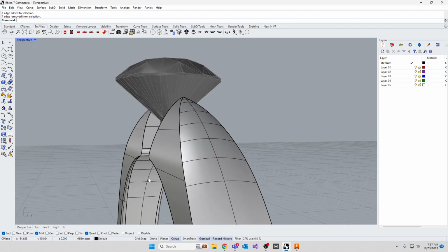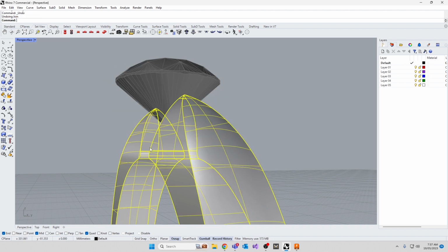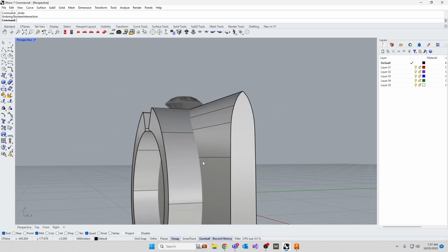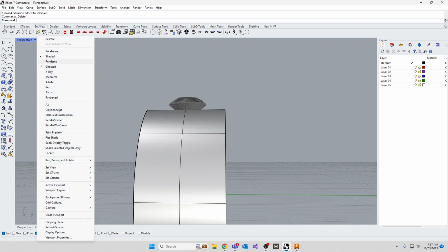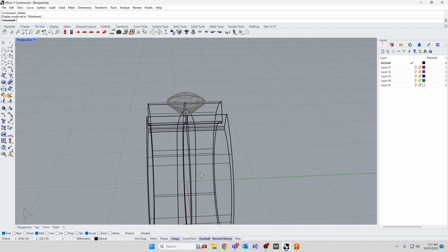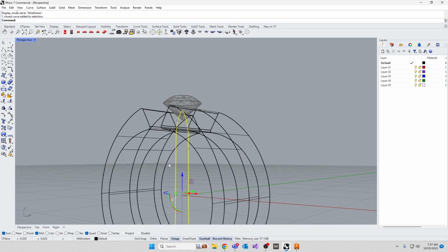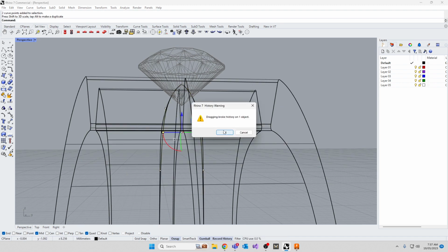So now you go to Cage Edit, or you go backwards, Control Z, and you bring this side view we had. So let's go all the way back again before we did our booleans. At this point, remember that curve we had here? You'd have to go back into the curve, wireframe, find that curve. So we had the problem here. You'd have to taper those 2 points back in towards each other so that we're up a little bit tighter up at the top.